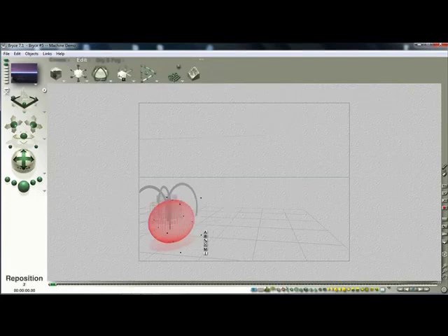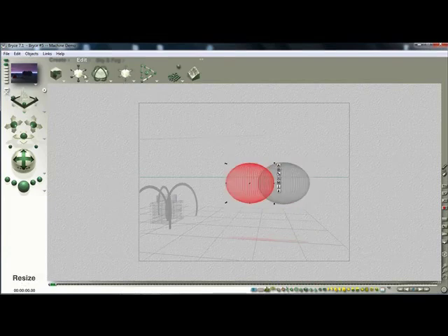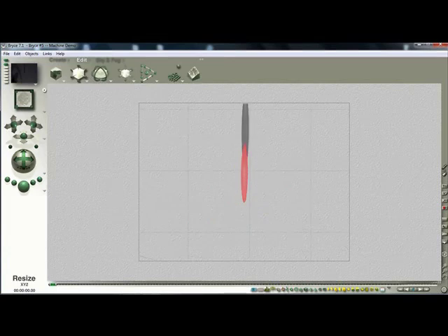Okay. Moving on here, I'm going to create a sphere. I'm going to create something that looks like maybe a capacitor, so I'm going to create a disc here. I'm going to flatten this circle. When I rotate it, you can see I've just flattened it, dragging in some of the axis points. And I duplicated it. Then I'm going to do a couple of Boolean intersections with these two spheres that I'm duplicating. They're basically going to cut some pieces out of the center disk or the center sphere.